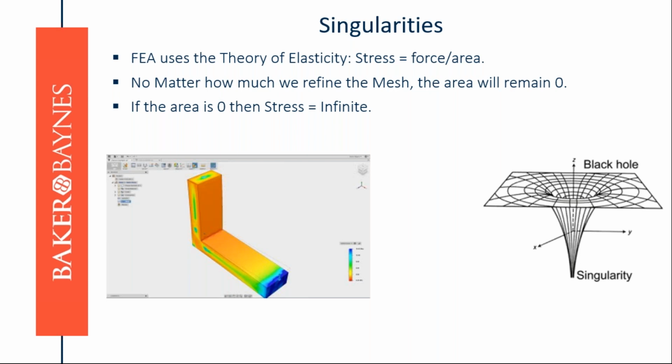So these should be avoided because it could also sometimes affect the results that we're getting in the long run. So the golden rule sometimes is refining your mesh often enough. So generally start off with a bit of a coarse mesh, go finer, finer, and finer, and compare the results between the two, because the more finer your mesh, the more accurate your results generally is.